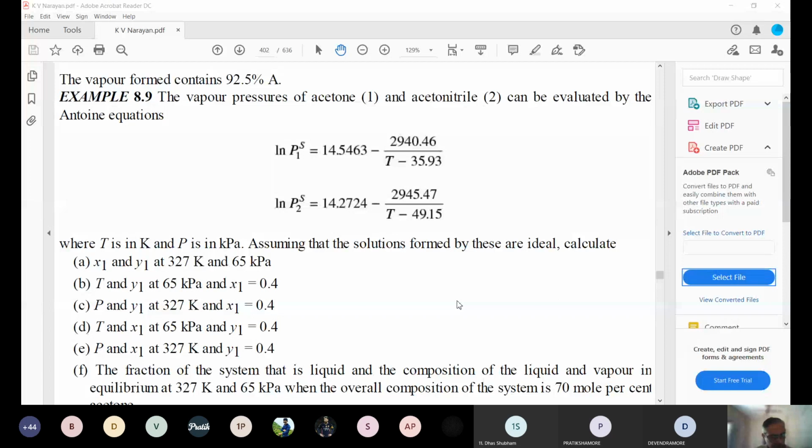If for 5 degrees we have a 10 kilopascal change, then for 1 degree how much change will it be, roughly? It's interpolation, it's not exact, it gives an idea. 2 kilopascal, right? So for 5 degrees change in temperature the vapor pressure or total pressure changes by 10 kilopascals. So for 1 degree change in temperature, it will be roughly changing by 2 kilopascal, right?